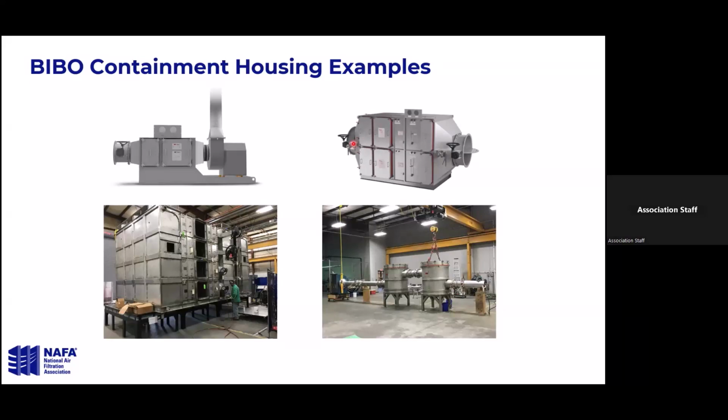And depending on what's in that housing, there's a certain amount of time that they're going to run that through so they can get the log kill that they want on that particular organism, to render it basically inert or killed, so that you can do a more safe change out or test of the filter on those housings.